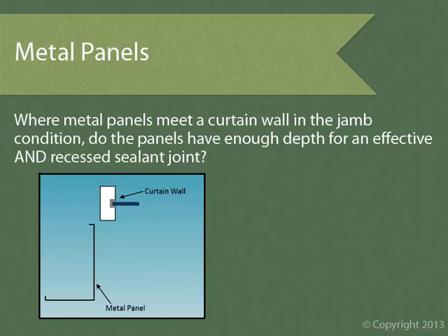For a block diagram, this may look just fine, and there may not appear to be any problem with a casual observation. But let's look at what happens when we add the sealant joint to this detail. There's the problem. When facade components intersect corner to corner, the resultant sealant joint will be large and unattractive. As you can see here, we might end up with a great big, angled, maybe 2-inch wide sealant joint.